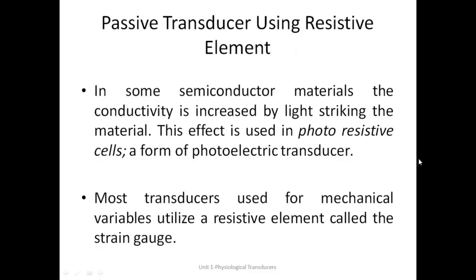Another possibility is that you can have photoresistive elements. Photoresistive elements are devices or materials which are very much sensitive towards light. As the light rays fall on the element, the electrons break open, and the conductivity increases, which means the resistivity is decreasing. If the resistance decreases, only then will the conductivity increase, right?